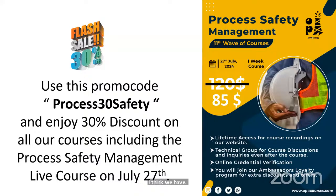What is the difference between HAZOP and FMEA? Yeah, it's FMEA. The difference is the application. HAZOP is a risk analysis technique used for identifying deviations in your plant. It uses nodes, dividing your process into small parts and studying the deviations in these small nodes. The deviation leads to consequences, which lead to incidents. So from the study, you can set controls to prevent these deviations from happening. This is HAZOP, simply a comprehensive study for the plant.